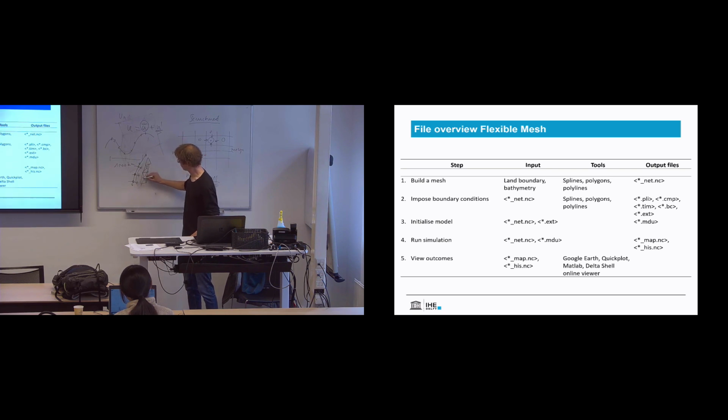Like so, but still you can just shoot out these. So I don't have to change my boundary conditions. And at initialization, my model automatically finds out which of these cells are boundary cells, where it has to apply the conditions. So if you have a different design, just change the grid and all the rest stays the same. Is that cool or what?